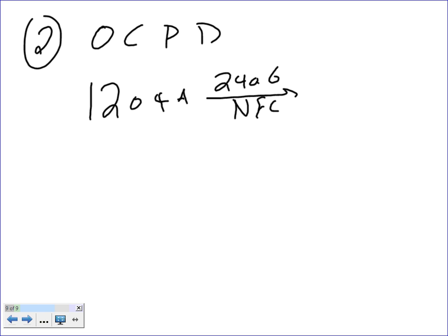No, you don't have to match. Where you don't have to, you're going to see, you don't have to match these, because sometimes, guys, the panel size is very large. You don't have to match it. The conductor, you will. So this will be 1200 amps. Is it wrong if you match them, Spencer? No. But sometimes you really end up with an 800 amp panel, and all you need is just 600 amps out of that. Should I jump 200 amps higher? That's a third more. What's the problem with jumping?